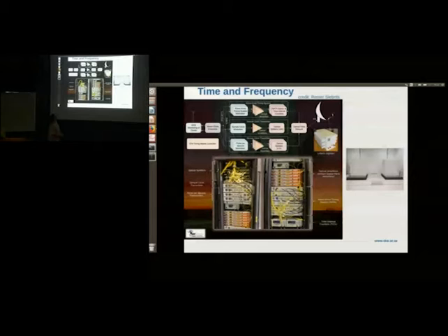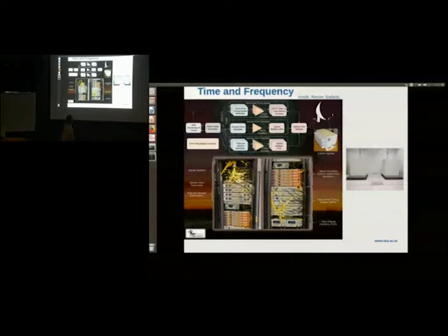So next, I would like to tell you a little bit more about the time and frequency reference subsystem. This is the subsystem that provides timing to the telescope, and it also provides the pulse per second for the telescope. So we have two hydrogen masers provided by T4Science, and the time and frequency reference group consists of the Karoo array timing system, the sample clock generator, and the pulse per second transmitter.